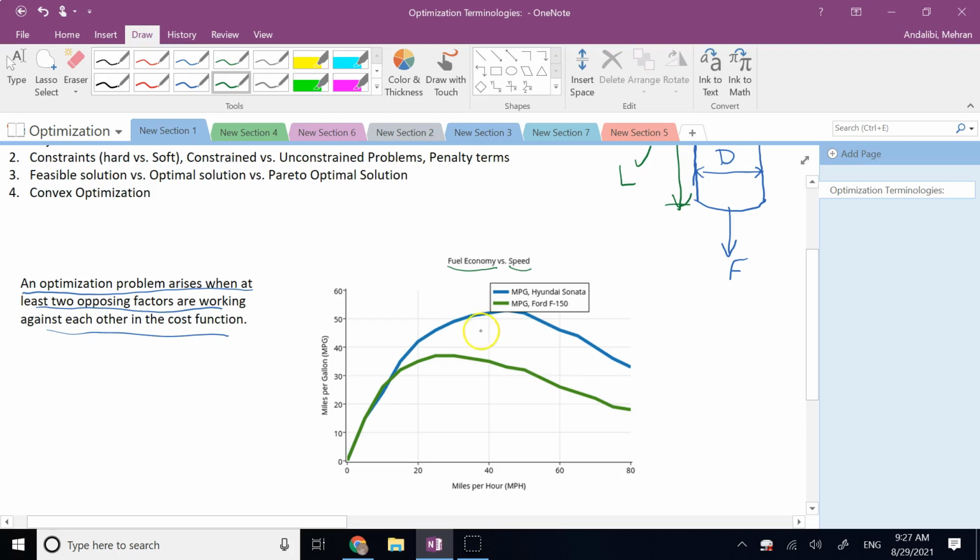That's fine. But when you are running too fast, now you have a lot of expansion, right? And your combustion is happening so fast that you have a good chance of not burning all of the fuel that is inserted into the chamber and losing it a little bit. The chance of leaking goes up. You also have rolling resistance showing itself, although it doesn't depend hugely on the speed, but the air drag does.